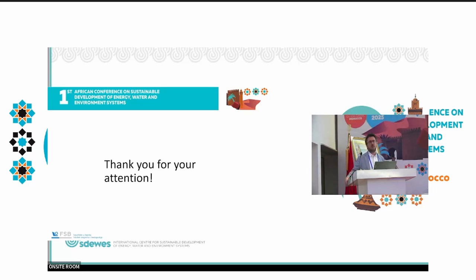So from the district cooling point of view, I think the key issue is this holistic synergy that you get on a system level. And you need to be sure how to valorize it and how not to create certain resistance from the final consumers. So you will never push a district cooling or district heating system in a rural area where you have low heat demand buildings. But if you have a very densely populated area with huge heating or cooling demand, like city centers, then you need to frame the building codes and urban zoning codes in a way that you give some kind of prioritization to this type of systems.